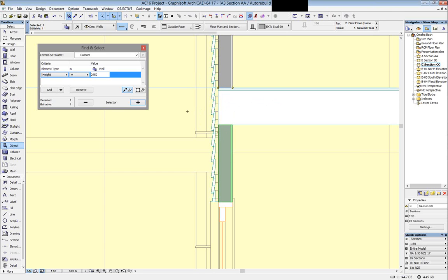So if I was once again using my scheduling ability in ArchiCAD to say what is the area of the interior wall, so I can calculate how much paint I need or how much wallpaper I need, it's giving me the exact square meters. If I change the floor-to-floor height and go back into it, of course that changes. If I change the floor sandwich thickness and rerun the schedule, once again it's real BIM stuff.